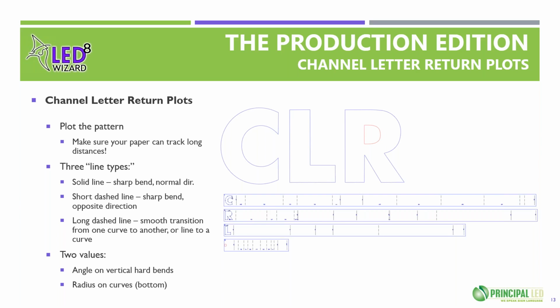So you would negatively offset the letters by the return amount, by the material thickness, say 0.04, and then you would run the tool with a 0 offset, and that would take care of it. Depending on your equipment and the way you're doing it, there's a little bit of testing involved, so I certainly suggest testing with one letter first. But yeah, it's a great question.